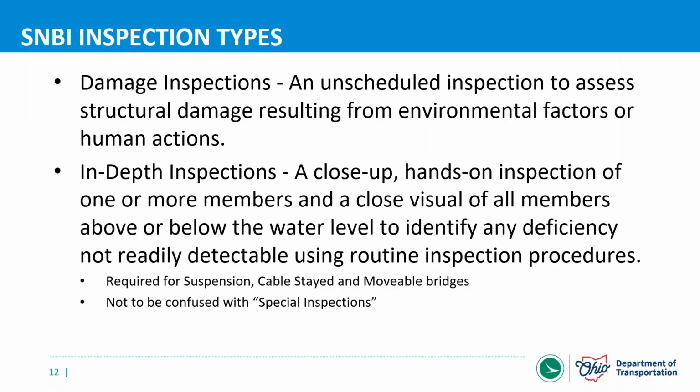In-depth inspections, not much has changed here with the previous guidance, but now we can actually code these as in-depth inspections, right? We have the choice to do so. So previously we didn't have an inspection type for this, so a lot of times it was coded as special inspection, and we want to get away from coding in-depth or complex bridge inspections as special inspections, and I'll talk about special inspections on the next screen or on the next slide.